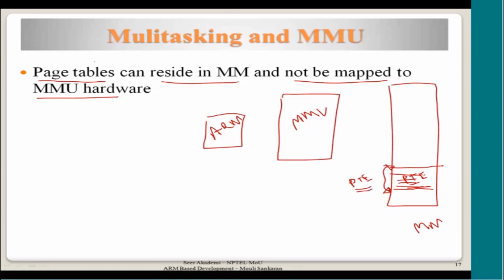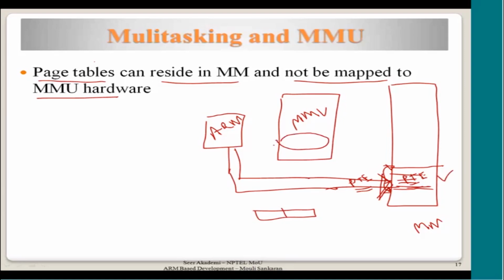They have the translation information, relocation register information. But if I say that even to access the page table, I need the help of the MMU, it is like expecting something which is not possible. See, we want to look at these values to configure the MMU, correct? Because now the MMU is raw, it is not even configured.